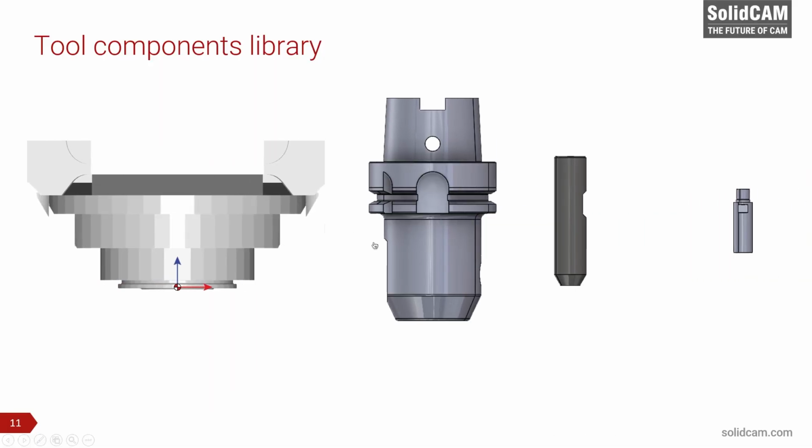In this video, I will demonstrate the essentials about components, connections, and their manipulations through the connection page. Let me start first with machine definition, and in this particular case, a spindle. Each spindle actually consists of one or multiple stations, and in this case, the spindle has only one station defined with an origin and the coordinate system with its direction.